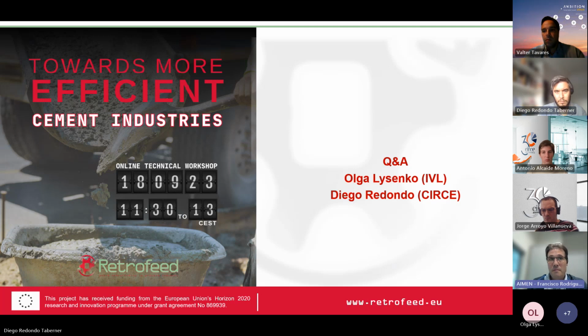But the technology is mature. After that, we can decide to go for a thermal camera in the short wave infrared range or in the long wave infrared range. If you want better quality images for segmentation and size estimation, you have to go for short wave infrared. If you want more precise thermal information, you have to go for long wave infrared.